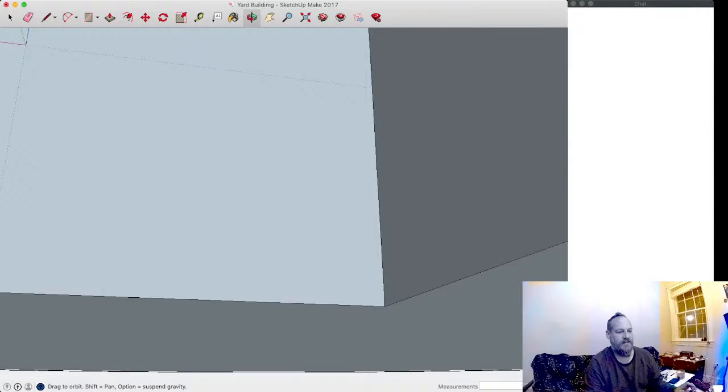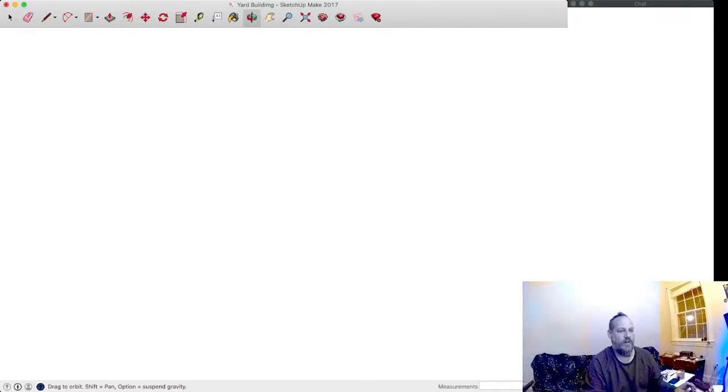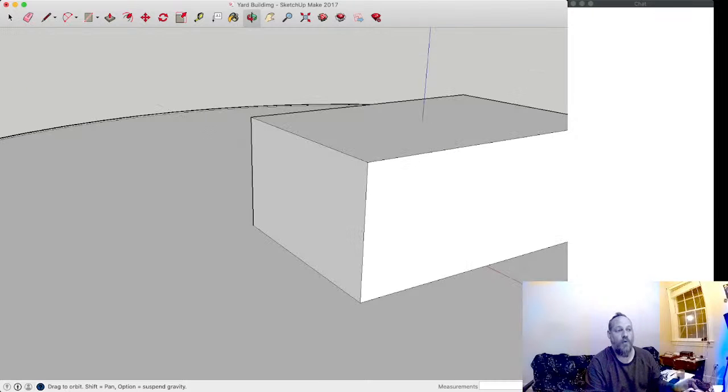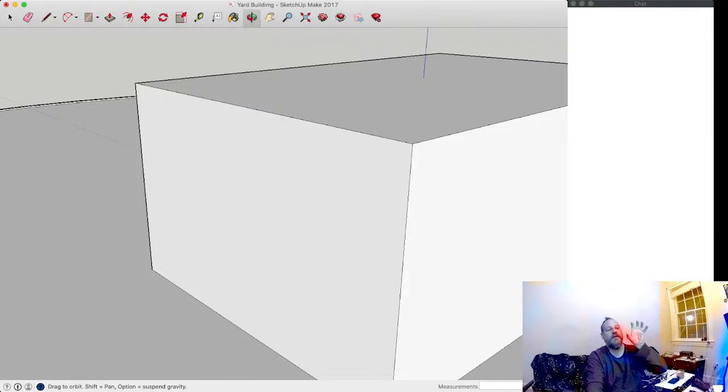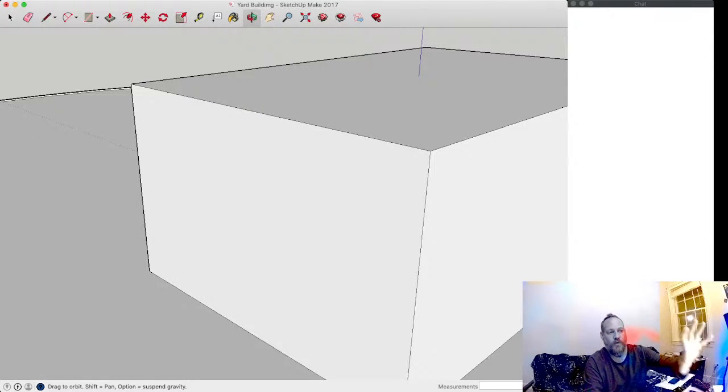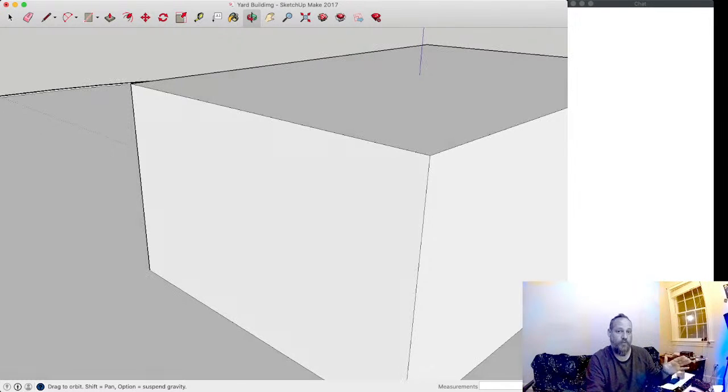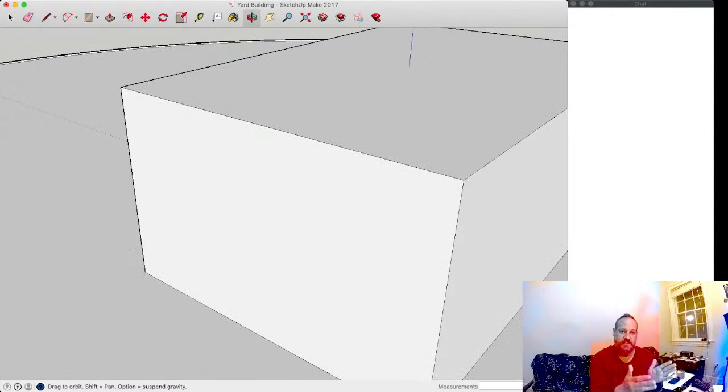And you go from a white wall on the outside to a gray wall on the inside. There's no way you can make the outside and inside this natural white, because SketchUp tells you one side's white, one side's gray, so you know what side is the outside, what side is the inside. All right. You also want in your spatial, or in the metaverse, to have walls that seem realistic. So generally, a wall is not paper thin. You're going to walk up to a wall and be right outside. Even my Airstream has a 3.5 inch thick wall. So this paper thin thing isn't going to work.